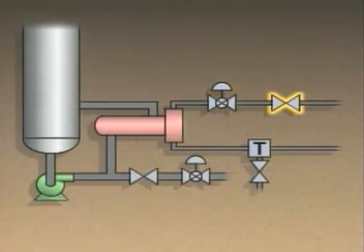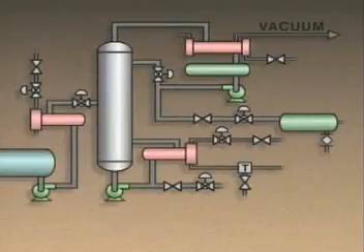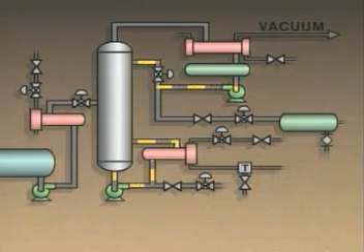An isolation valve in the steam line is closed as well to ensure that no steam reaches the reboiler. The reboiler's circulating pump is left on for now to help cool the liquid and equipment. At this point, there's no feed going into the column, and the overhead and bottoms mixtures are being recirculated.